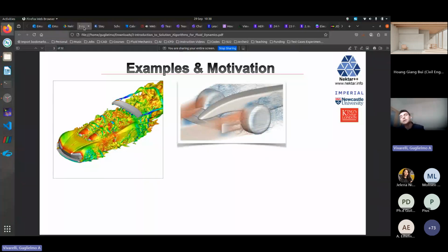You're in the incompressible range. So now the Mach number is beneath 0.3, or density variation beneath 5%. And this is of particular interest to the external aerodynamics of the automotive industry. And on the left, you can appreciate the complexity of the geometry. But one of the main things I want to bring your attention to are the different length scales that appear in the configuration.